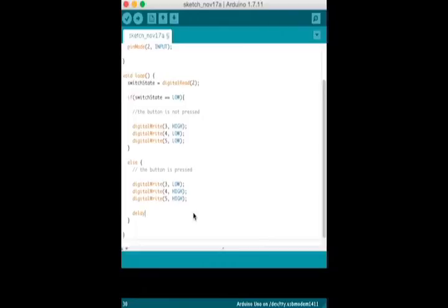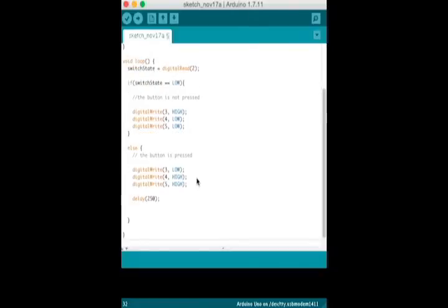To get the red LEDs to blink when the button is pressed, you'll need to turn the lights off and on in the else statement you just wrote. To do this, change the code to look like this. It has a delay with 250, so that's wait for 1/4 of a second. So those must be in milliseconds. And then I want these ones to blink.